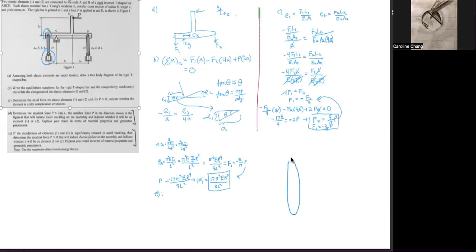Because imagine if we have two pinned ends, but both of these places constrain this beam from bending outwards. So from the YZ perspective, both of these ends behave as if they were fixed ends, because we have our pin over here and our pin over here, but there is something constraining it from bending outwards.